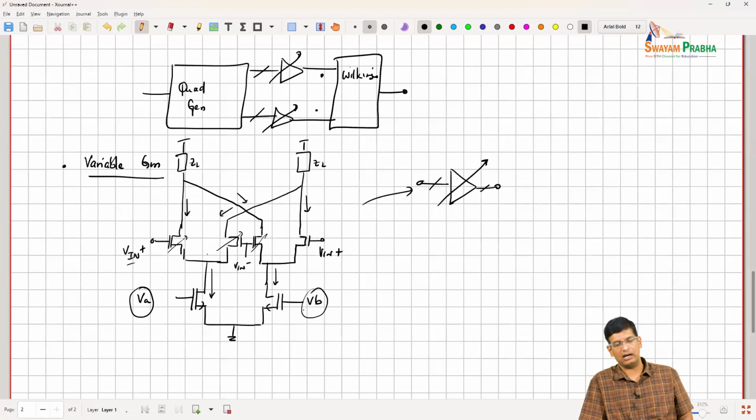So in this topology, the control of gain is sort of simplified, right? Because you are controlling the gain by controlling the I, and I is controlling GM, right? So if GM is proportional to I, then you can have linear control. If you see some square root I dependence, you can correct for that by applying appropriate control voltages. So it simplifies control generation.